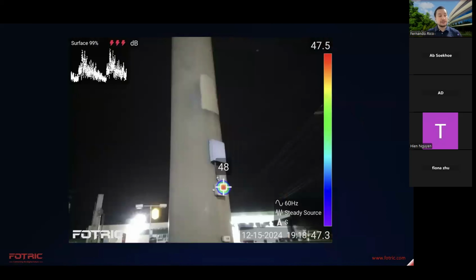Another interesting application that I really like, that prevents the guessing during an inspection, is how you can determine whether there is partial discharge inside an electrical enclosure. When partial discharge occurs inside an enclosure over time, those discharges start ionizing the air inside. By doing so, they create a more conductive, let's say, micro-atmosphere, and the ozone starts reacting with the material of the insulating components to create nitric acid that in turn degrades the insulating properties even more.